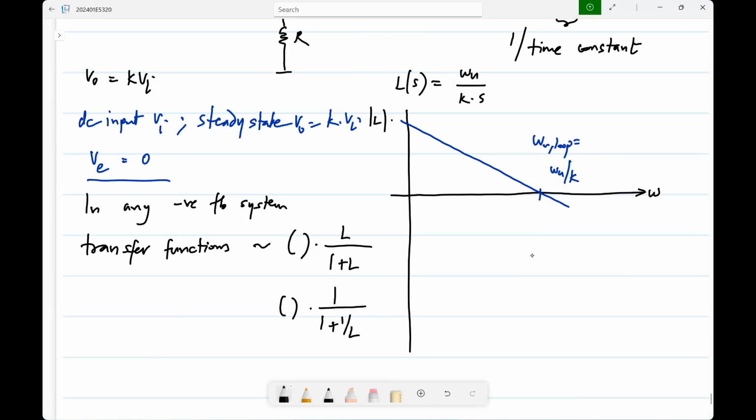So what is the meaning of very large loop gain? That means actually it is at those frequencies that you have virtual short. Okay. Because of that very large loop gain, that error voltage will be small, may not be 0, but will be very small. So approximately you have a virtual short. Okay. So basically this factor is what makes all the good stuff due to negative feedback possible.